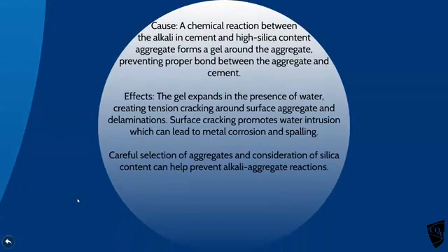The last one here, I think, is the carbonation one. That one was chemical before, I believe. It's a chemical reaction between alkali. This is the alkali silica one. Sorry, I should have put the heading on here. Alkali silica, otherwise known as concrete cancer, it's an interaction between the alkali in the cement and high silica content